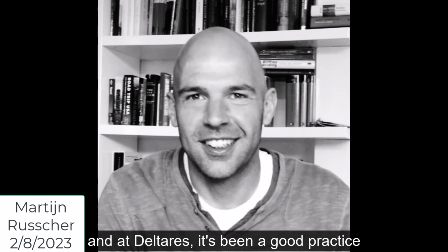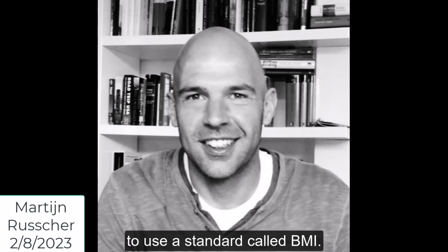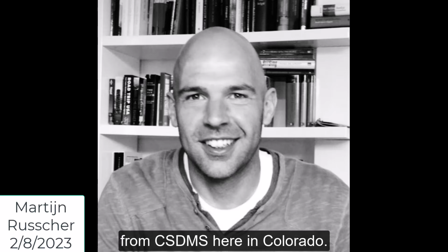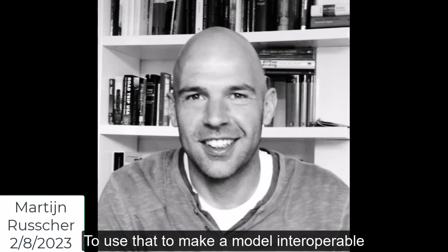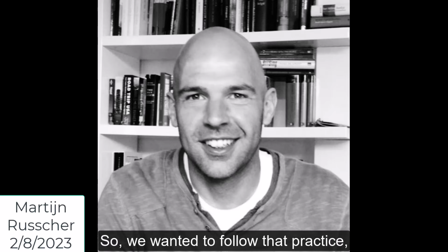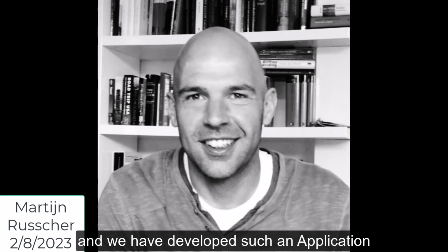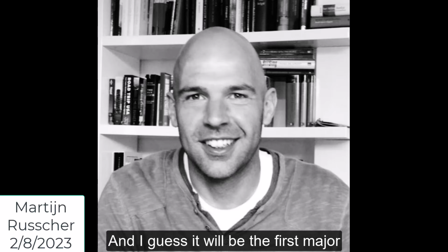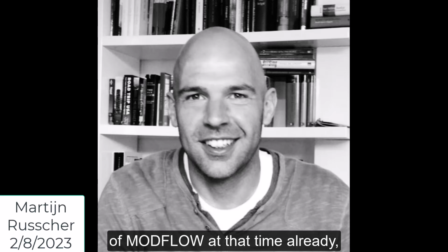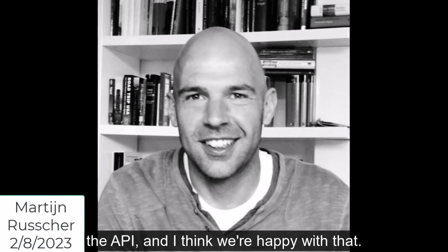And at Deltares, it's been good practice to use a standard called BMI. It's not really a standard, but known as BMI. It's from CSDMS here in Colorado. We use that to make a model interoperable without being too invasive into the model code. So we wanted to follow that practice, and we developed such an application programming interface for MODFLOW 6. And I guess that was the first major contribution. It started as a side project, because the piece of work that we were basically going for at that time was the parallelization of MODFLOW, which was delayed because of our work on the API.